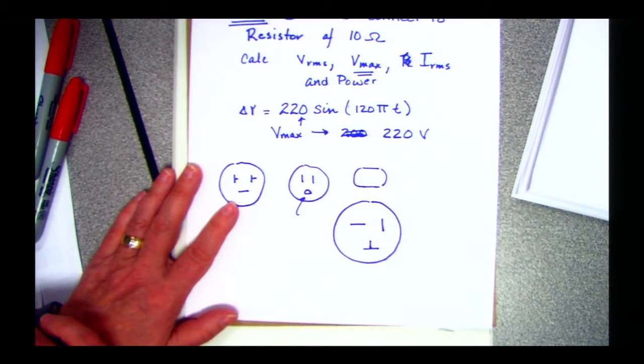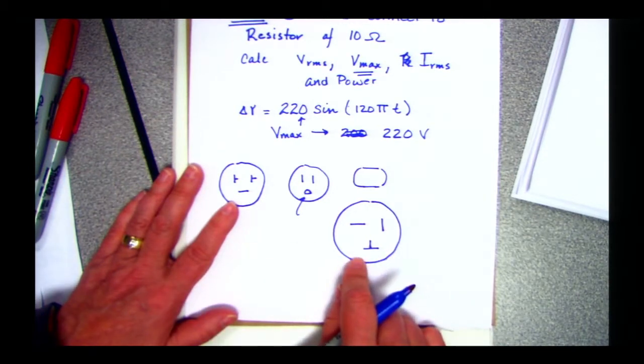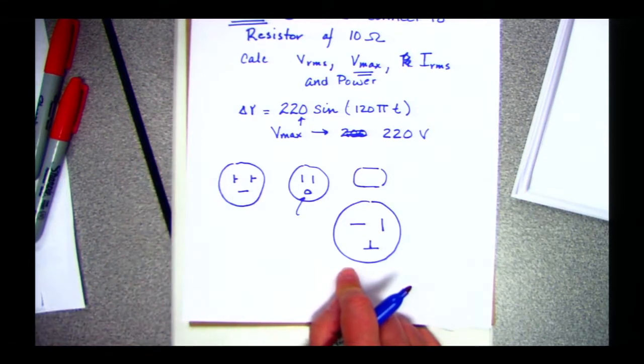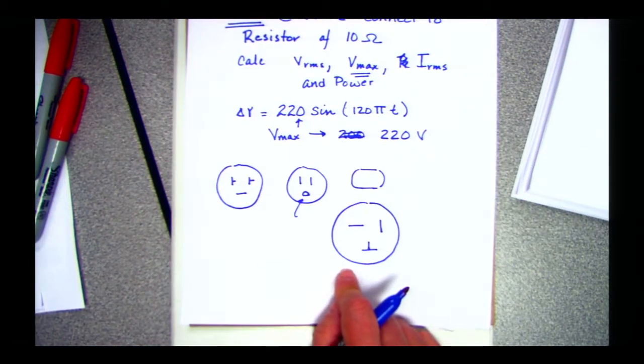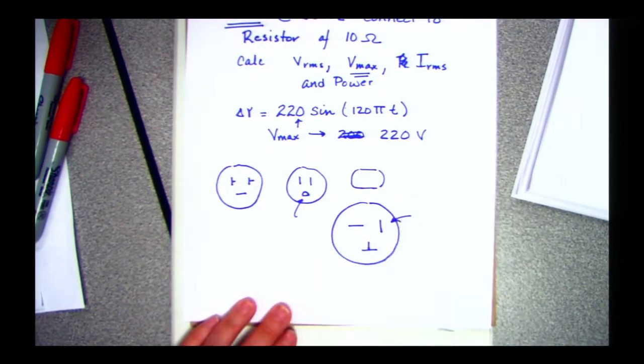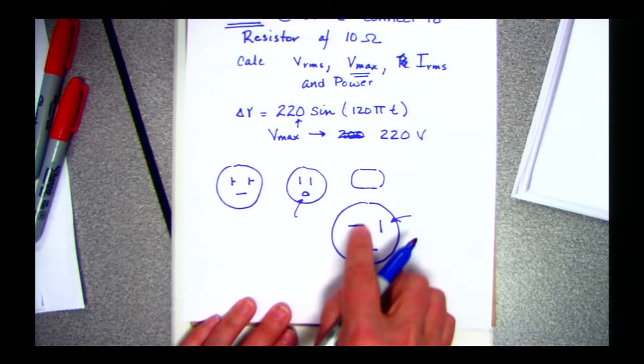So you have to actually look, and there are actually two, for your dryers, when you buy a dryer, you actually have to buy a 220 pigtail. And that's what they're called, pigtails. You have to buy a special 220 pigtail, and there's two styles, so it depends on what your house is wired with, which kind of style we have. And we're going to find out why none of these are ground in a 220.